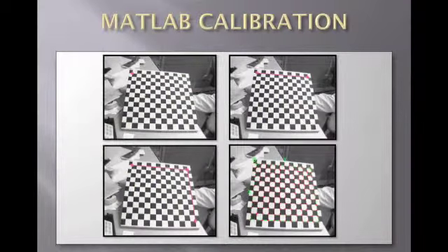Here we're going to show a brief overview of how MATLAB can be calibrated by using a collection of known targets or images identifying various key features. Once calibrated, the image may be corrected for aberrations, distortion, and other resolution issues. In our case, we used a large checkerboard pattern to calibrate the system. As can be seen, MATLAB identifies the largest inner square and then all the black to white corners.